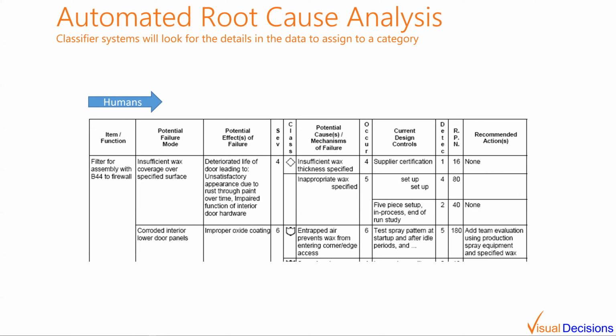And then we list out what are the different potential failure modes for that operation. Then we get into the potential impacts of those failures and the different causes of why that failure would happen. And then we can start to look at, what are the different things that we can do to detect that particular cause of failure is actually occurring.